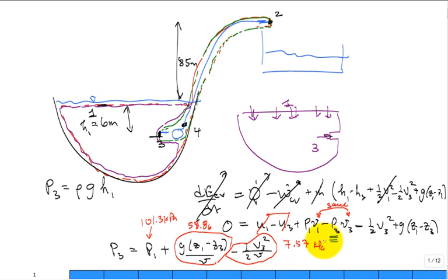It's accelerated, and it's now moving into the pipe. You have to have suction to get it to draw into the pipe, and that's the suction due to the speed. From the energy equation, you see that. So somebody may say, this was roughly 60, and this is roughly 8? 60 minus 8. If you neglected the suction at the inlet to the pipe, you missed it by the difference between 60 kilopascal and 52 kilopascal.